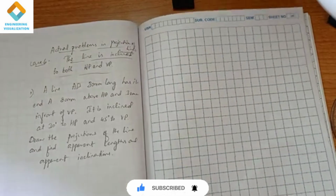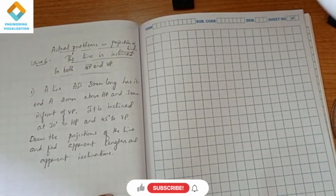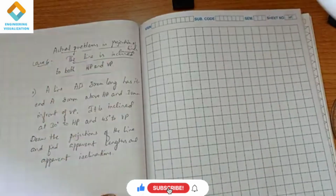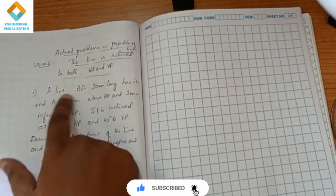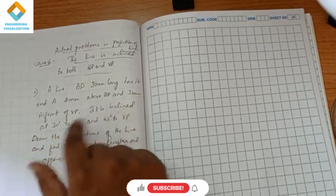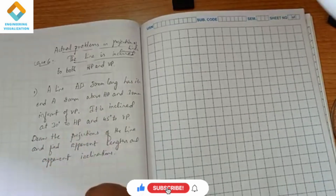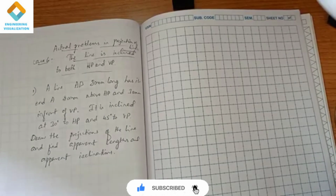This is case 6, where the line is inclined to both HP and VP. A line inclined to both HP and VP is the actual problem in projection of lines. So now we are dealing with the actual problem. The line AB, 80 mm long, has its end A 20 mm above HP and 30 mm in front of VP. It is inclined at 30 degrees to HP and 45 degrees to VP. First I'm going to draw an XY line here.